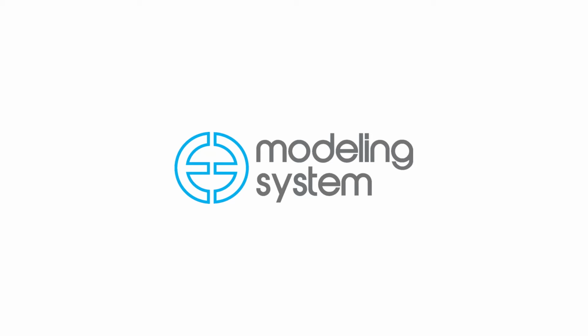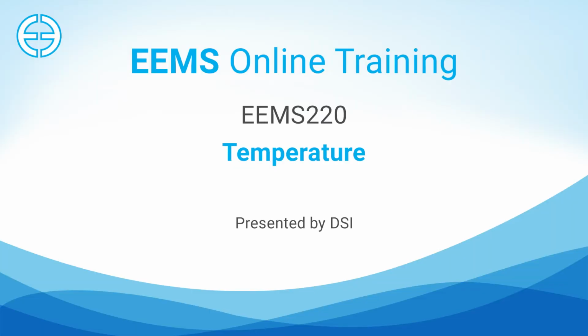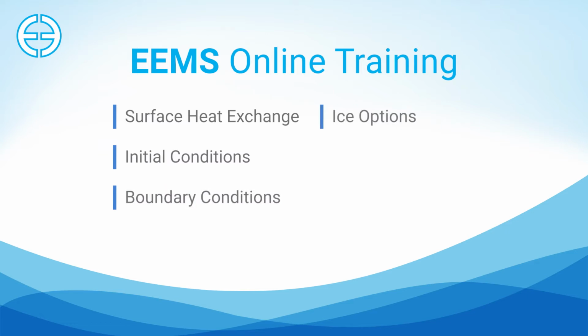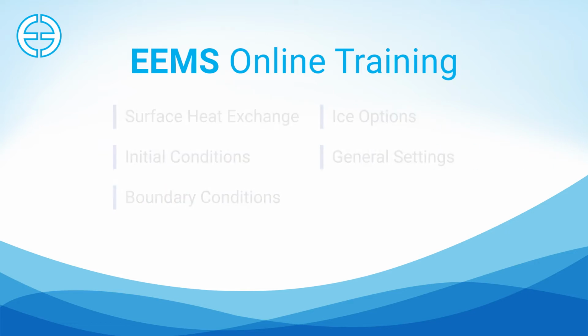Welcome to EMS 220. In this video, we will examine the graphical features of EFDC Explorer that support modeling of temperature in a water body. There are 5 components of the graphical interface: surface heat exchange, initial conditions, boundary conditions, ice options, and general settings. Let's go.